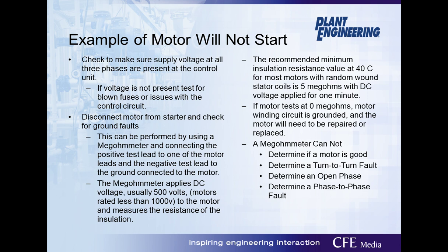Please note that a megohm meter cannot determine if a complete motor winding circuit is good, nor can it detect any turn-to-turn or phase-to-phase faults. These tests will need to be performed by more advanced motor circuit testers.